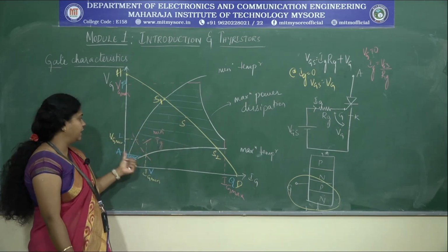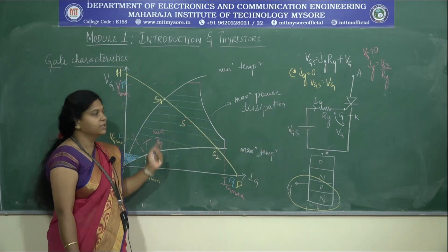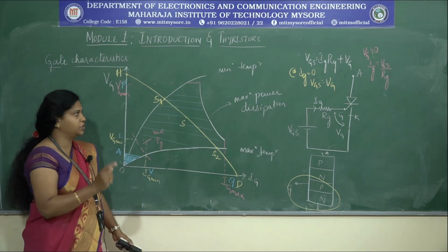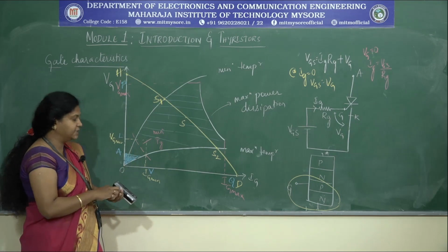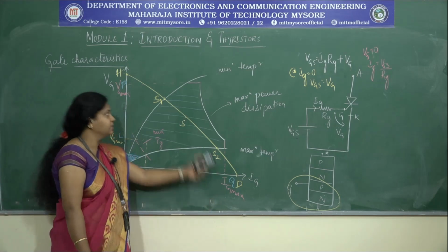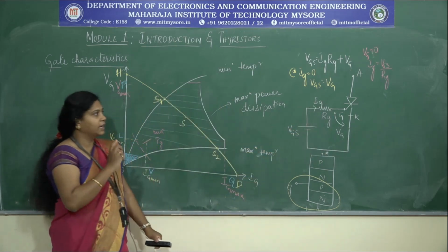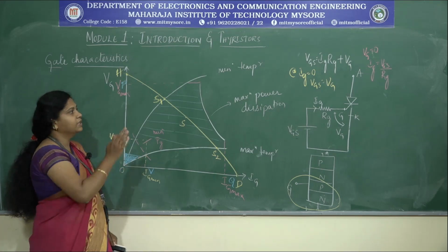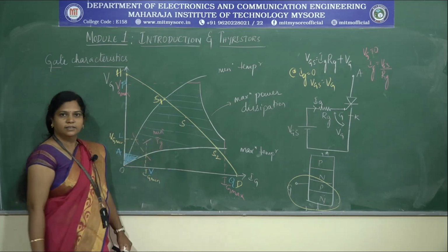Now, if you are giving the voltage and current across this gate terminal in such a way that it is satisfying this, there will be a perfect turn on of the thyristor, within the allotted duration of time. Now, similarly, we have to find out what are the maximum and minimum resistance. You have found out the gate current and the gate voltage. Now, you should find out the condition where the maximum or minimum resistance you are choosing is sufficient, allowing the current to flow through the thyristor.